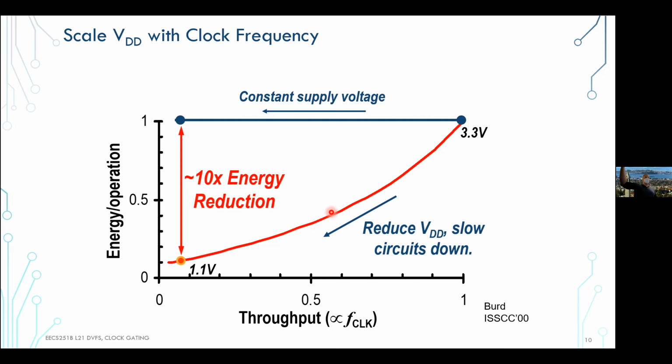Because on one end, I'm wasting energy because my VDD is not low enough. On the other end, I may be trying too aggressively, and actually I have timing violations, so my design doesn't work. Right. So around this curve, there is some kind of buffer, right? Ideally, I want to ride it exactly on the curve, but normally I'd have to be a little bit above because of all the uncertainties we have in the system.